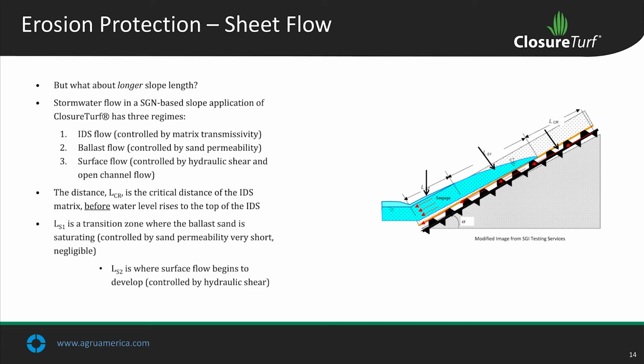It has a curve number of 94, and a C coefficient in the rational method of 0.76. Most of the water flows off of this system, so something you need to keep in mind. We'll touch on that a little bit here.